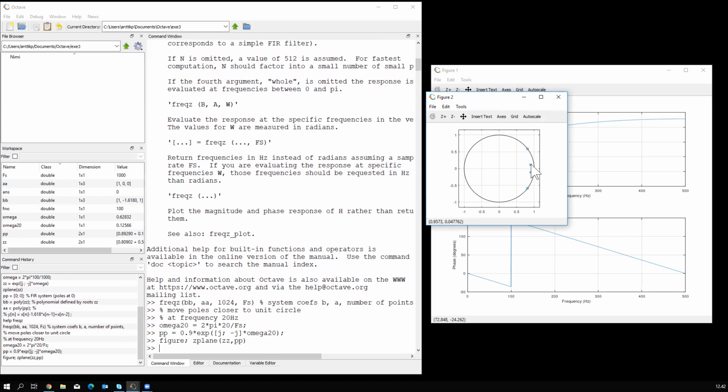So as you can see, this puts some gain near the low frequency here, because if you have j omega nearby, then the distance to this is very close, so you get a magnitude of about 10 times amplification, or more than 10 times, about 50 times more amplification.